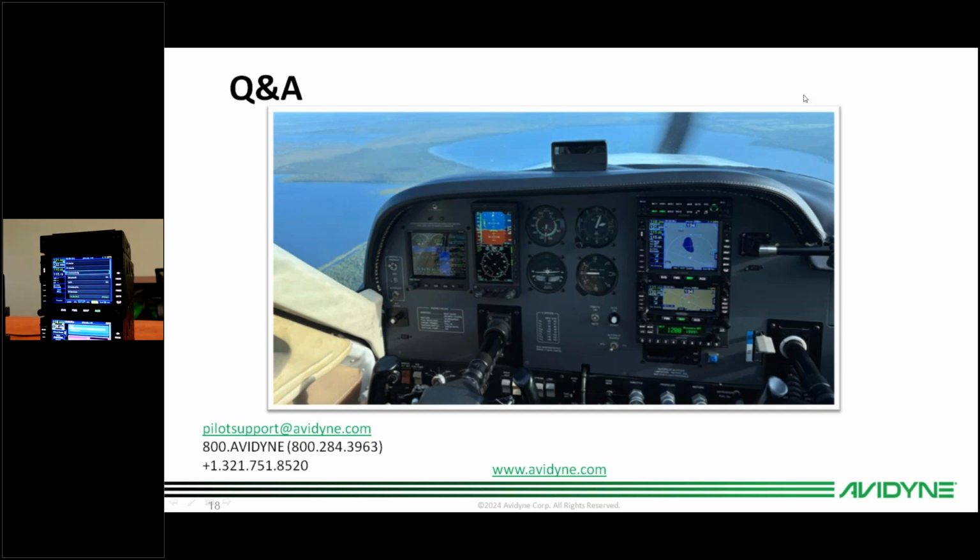If it's a GPS receiver, just like a Stratus, the IFD is not going to be taking that GPS data. It's just going to ignore it, taking ADS-B in data. So I don't see any problems with those things interfacing, as long as they can interface on Wi-Fi. It just might not get the traffic and weather to the IFD like you'd like it to, if you're trying to do that. But the flight plan transfer and everything, as long as it's Wi-Fi, should work.